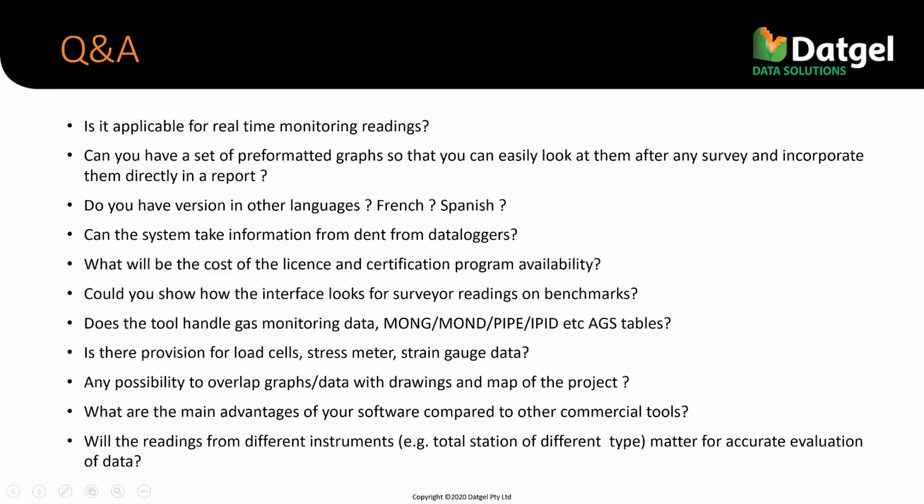So you have your boreholes, you have your lab testing, all in this one database. This database would need to be bigger, right? This is just the monitoring tables. But you can have everything in one, and you can present borehole data and other results on the same report if you need to. And you can export to AGS format from one system. All together, you get one AGS format file for all your other geotechnical data without double handling and copy pasting it back into gINT or some other product.